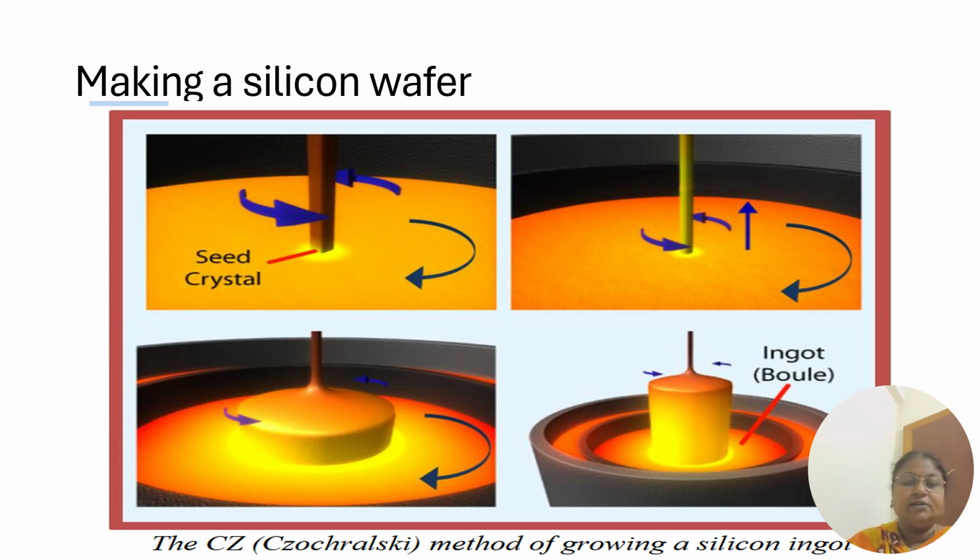molten silica is nothing. Many of you will be wondering, it's just sand. So this sand is available in the form of a molten part, and it is taken into a crucible which is heated to 1200 degrees Celsius in a furnace, and from that we have this pulling effect with what we call a seed crystal.